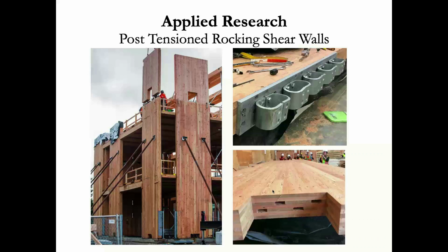Another application of our seismic work is this post-tensioned rocking shear wall that Levi mentioned earlier, and these are D.R. Johnson panels, of course, on our P.D. Hall building. There are these elements at the edges, these U-shaped flexural plates that act like a seismic fuse. So in the event of an earthquake, if you're not familiar with these, basically these walls are tensioned to the ground with these steel post-tensioning cables that run all the way through the panel through these channels that you see here.